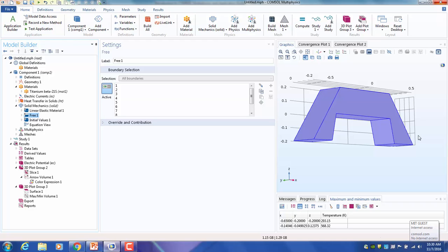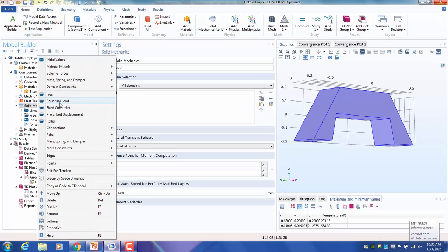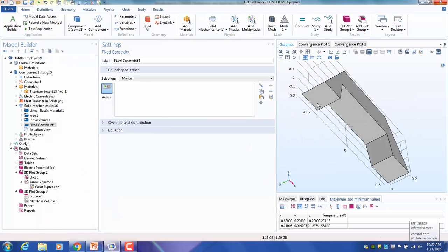Or if you know that the shape on one end doesn't change, you can glue the entire surface to another, say a fixed surface. That will of course be sufficient for eliminating the uncertainty here. All right, so in this case, we're just going to use the fixed constraint on the 2 feet. Actually, I could use the drop-down feet, which will assign the same condition: u, the vector of x, y, z components of displacement, all equal to 0.